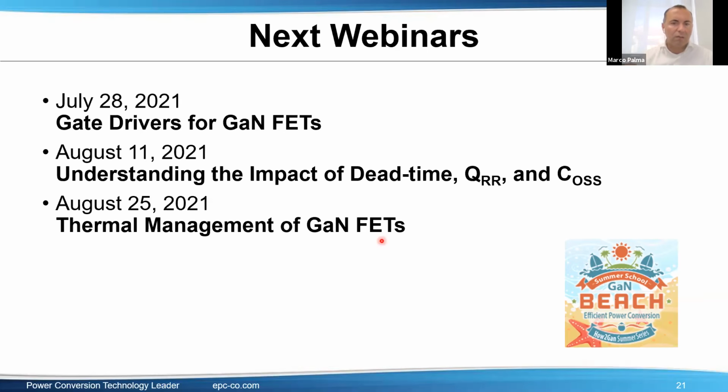But I can anticipate, at least by voice, what is happening, and we suggest using some devices which are threaded standoffs, which are mechanical devices with a threaded standoff inside, so they can get placed by pick and place machine on a regular SMD process, and they get soldered on the board.